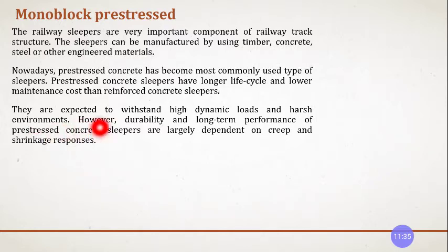They are expected to withstand high dynamic load. Dynamic means moving loads, right? The load which is in motion, in a harsh environment. However, the durability and long-term performance of pre-stressed concrete sleepers largely depend upon the creep and shrinkage response. How the creep occurs, how much creep occurs, and how you maintain it. Depending upon that, the lifespan of the pre-stressed sleepers is maintained.